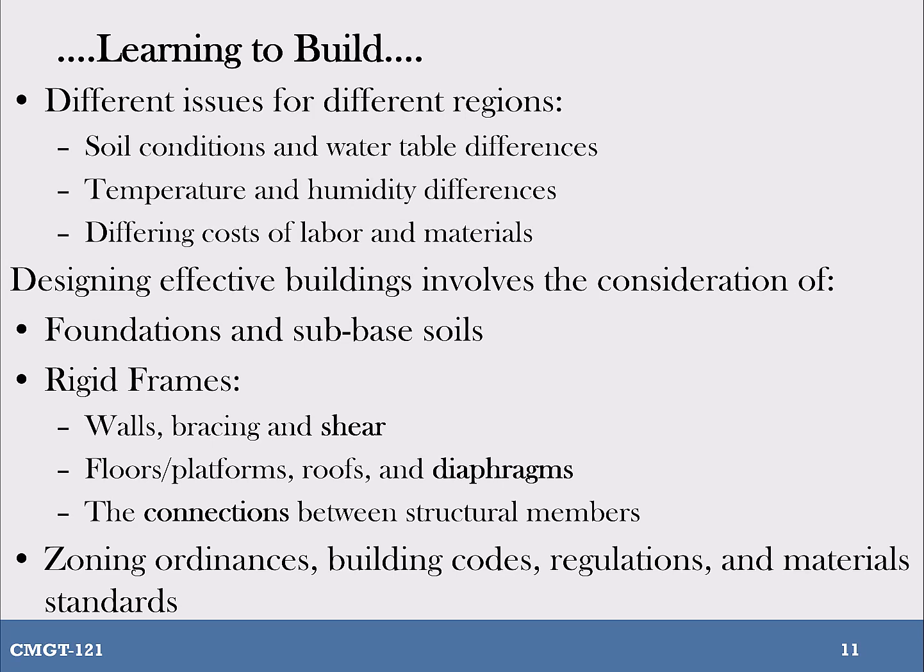In order for a building to hold together well from wind loads, from other forces, it's got all the walls and the ceilings, the floors, the roof, everything has to be tied together. And especially in this high wind climate that we live in, wind loads can tear apart a building, sometimes not by blowing it over, but actually exploding it by catching air underneath and picking up the roof and throwing it off like an umbrella.